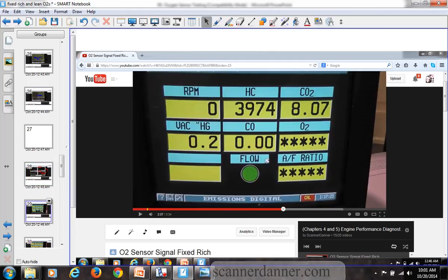You would swear by the smell of this exhaust that it was rich. It wasn't. Look at my CO percentage on this van at this point in time, right where that O2 is rich. 0. Now my O2 is dead, as you can see. That'd be nice to look at. Why does it stink so bad? Look at the hydrocarbons. Hydrocarbons are unburned fuel.